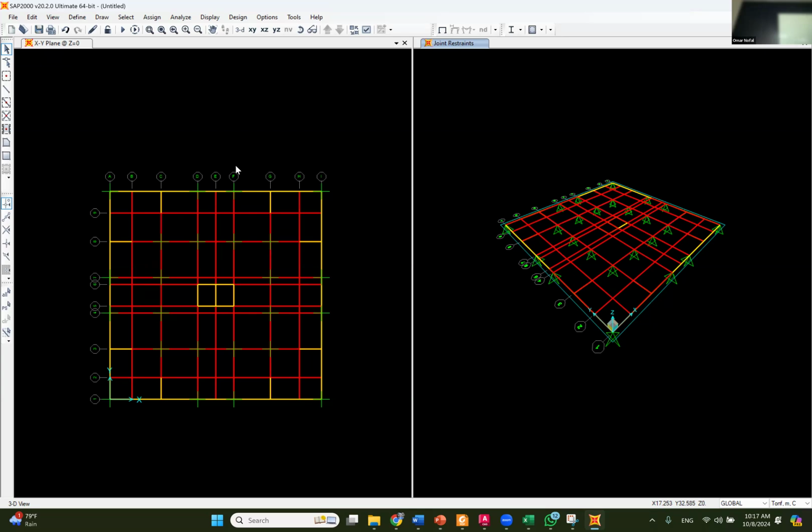Let's say, this is very important. Let's say that we at first divided them 5 by 5. If we divided them 5 by 5 randomly, you will end up with your hinges here and the mesh. Okay, the mesh is like this, the 0.5, and maybe the column in the middle is not connected to a joint. If the column is not connected to one of the mesh joints, the column is not going to feel that there's any slab here.